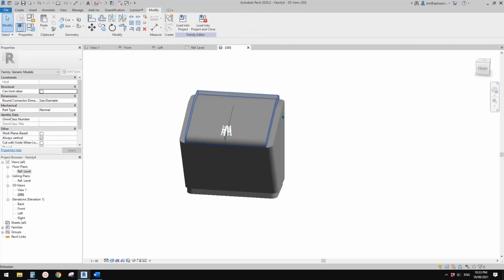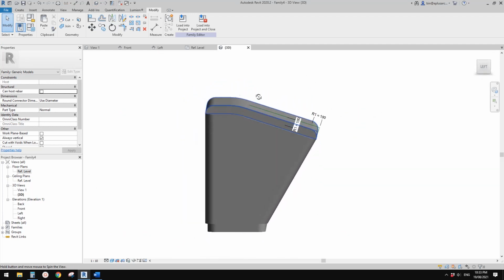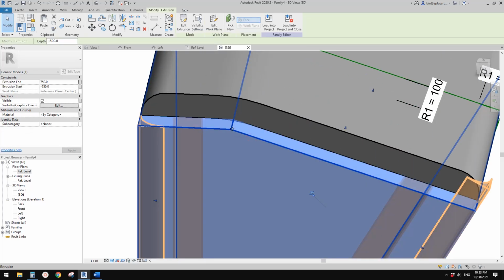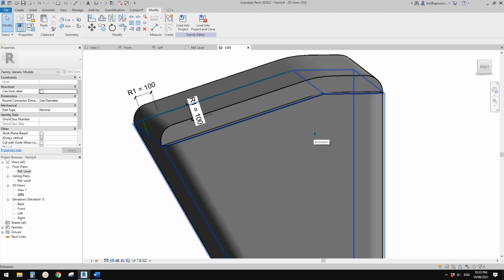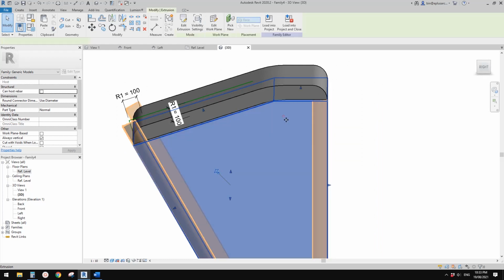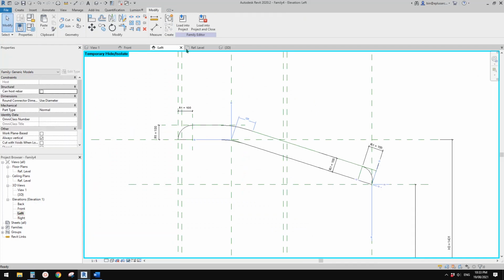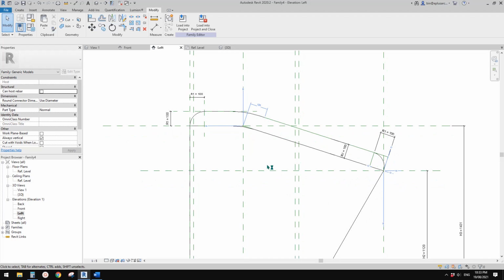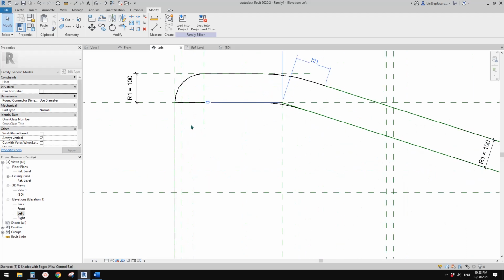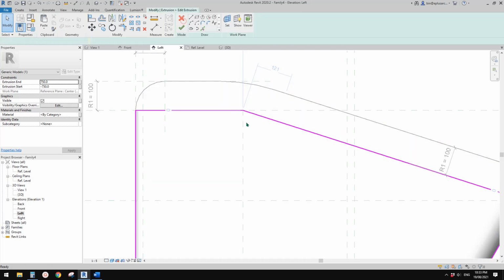So have a look in 3D view. Yep, that's almost there. Almost there. Oh, why is there a line there? Okay, so because when we created this solid, we didn't add a radius, that's fine. So we can go back to the left. So HR, let me just TL. Oh, looks like it's because of the scale. The line is very thin. But that's fine. Maybe change it to shade, SD, and then we just need to edit extrusion.